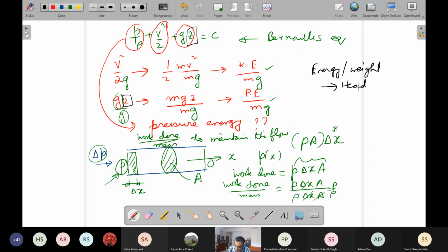This is important because typically in civil engineering or piping engineering, head has a length unit. This is often used to express the energy. So for example, typical civil engineers will say that it has say 10 meter of kinetic energy head. Something like that. So energy per unit weight.